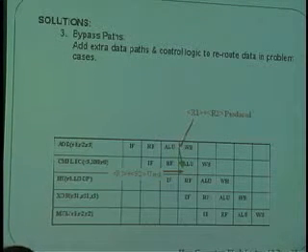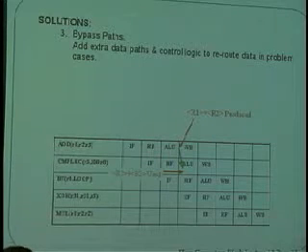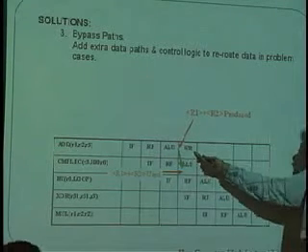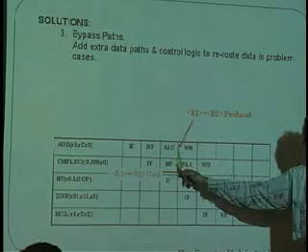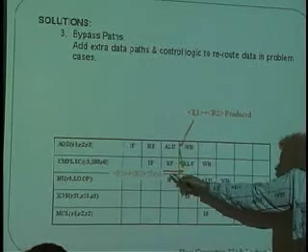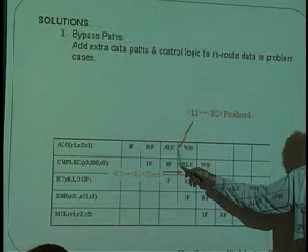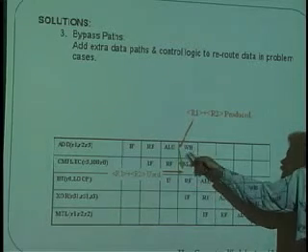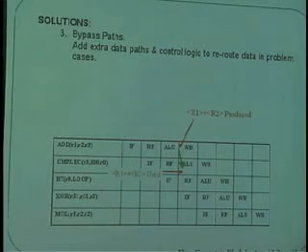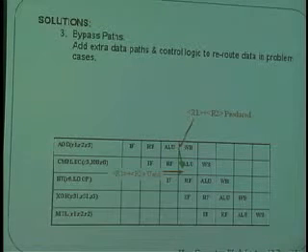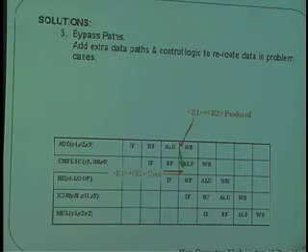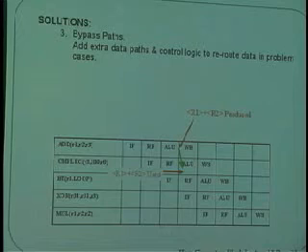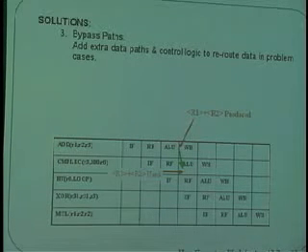And what it's doing is it's sneaking a peek at what is about to be written to the register file, ignoring what was read from the register file here because it's old and stale, and substituting that data into the ALU rather than what it read. And we're going to see cases where the data does not yet exist in the machine and you have no choice but to stall. How do you do this 1.5 billion times a second?